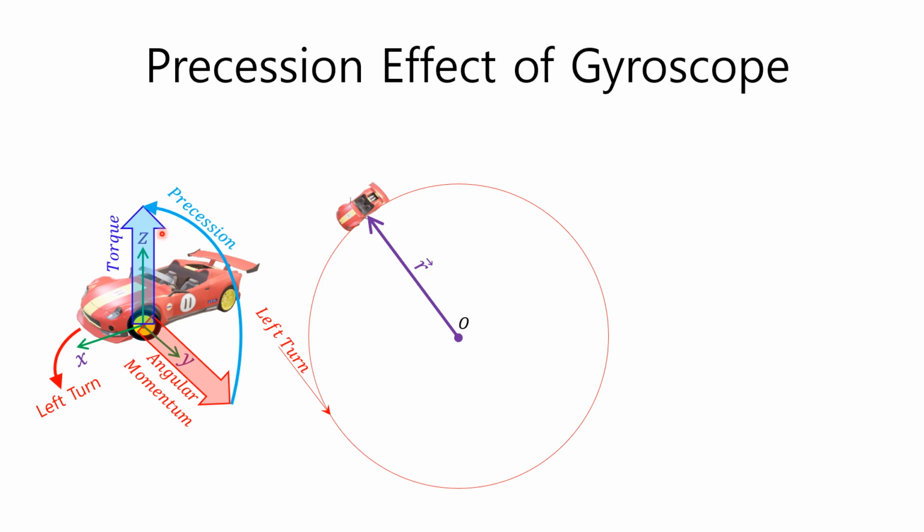On the other hand, since the tip of angular momentum arrow tends to rotate toward the tip of the torque arrow, a precession movement occurs about the positive x-axis. Therefore, a wheel overturning moment is created which tends to rotate the wheel towards the outside of the vehicle. Even when making a right turn, the wheel tipping moment occurs equally toward the outside of the vehicle, just as in a left turn.